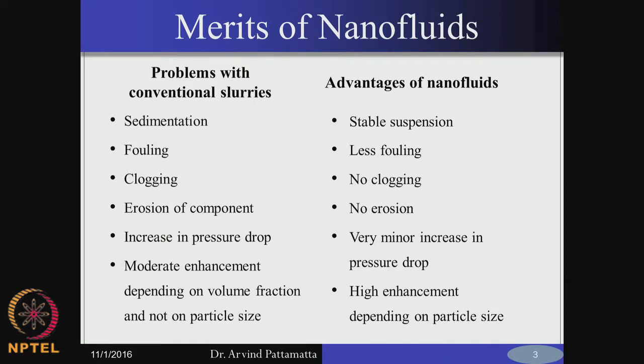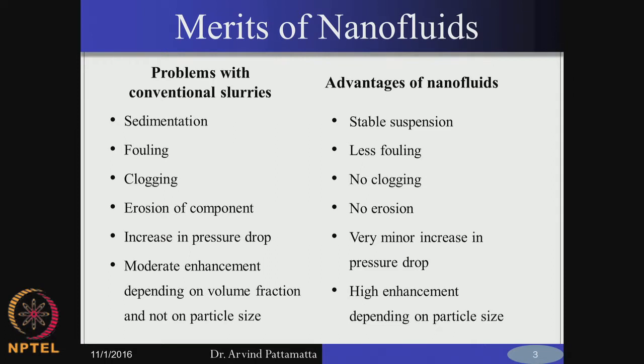And they can also lead to clogging whenever you use them in filters. These filters can be of the size of a few microns, and if you use large scale particles, they will simply block the filter passages. Also, a very important point is the increase in pressure drop. If you have very large particles, you have to increase the pumping power to pump the same flow rate, correct. So, your pressure drop is going up, and you can probably get higher thermophysical properties, but you have associated problems like these, which make them practically difficult to implement with colloids, but still colloids are popular in a certain sense, people use them in chemical engineering.